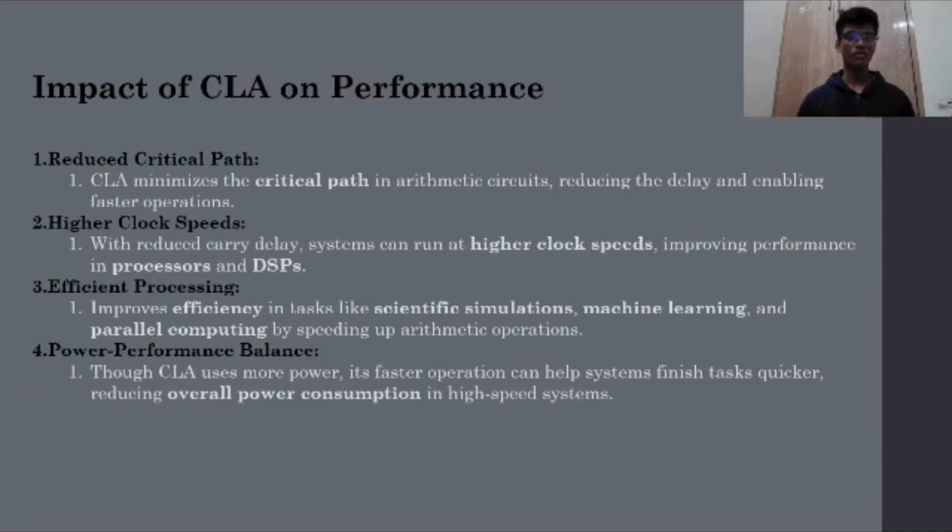Impact of CLA on performance. Reduced critical path. CLA minimizes the critical path in arithmetic circuits, reducing the delay and enabling faster operations. Higher clock speed with reduced carry delays. Systems can run at higher clock speeds, improving the performance in processors and DSPs. Efficient processing improves the efficiency in tasks like scientific simulation, machine learning, and parallel computing by speeding up the arithmetic